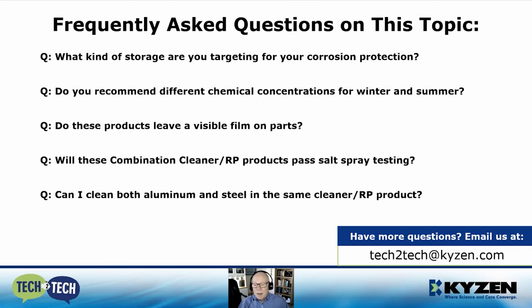Will these combination cleaner RP products pass salt spray testing? The answer is no. These are water-based RP products, and the RP will be rinsed off in even a misting salt spray test. Salt spray is normally used for coated products, like powder coated products, for example, to test the integrity of the coating.